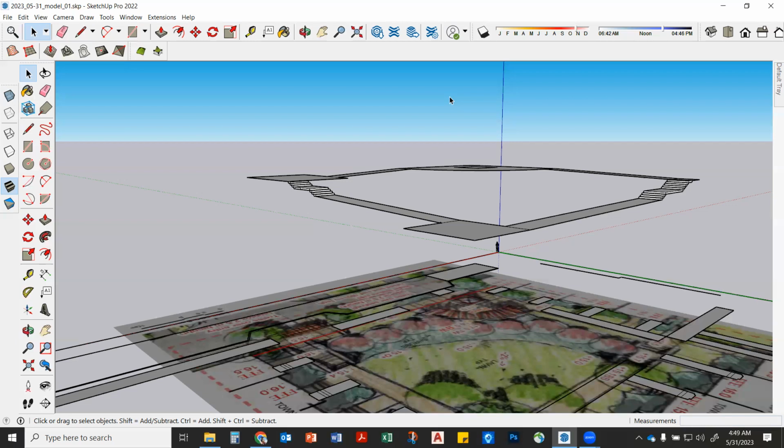Like you could say stair risers, like you have stair riser and you have like stair set, right? But if they're all in the same one, you can just explode it. Or you can go in and cut them out of it. You can do Control X, come out of the group, and then paste into place, and then it'll be outside the group. So try that, yeah? Because that's a good process to know.